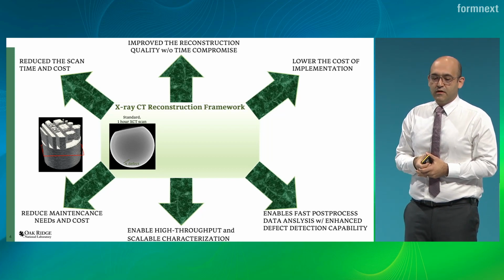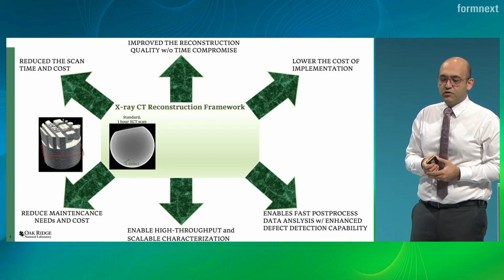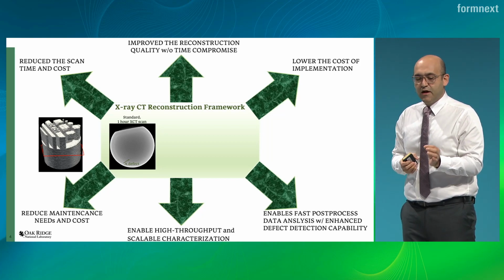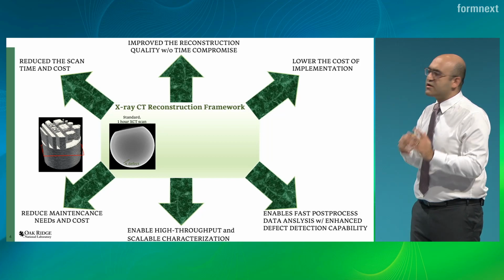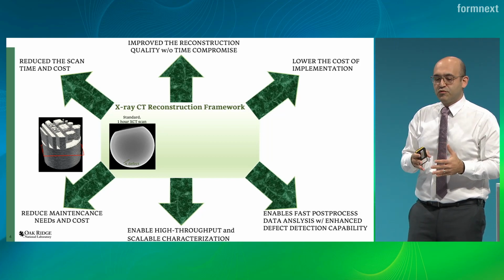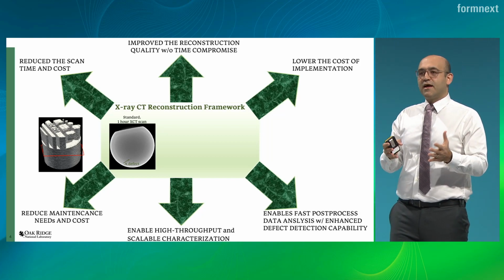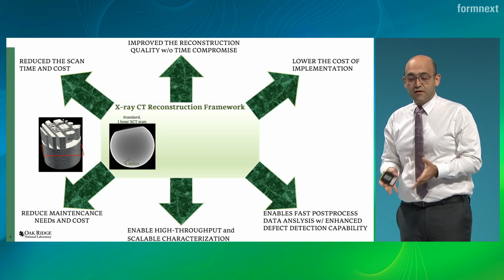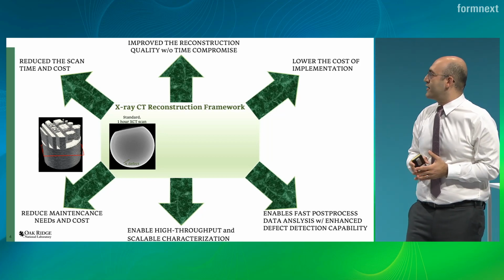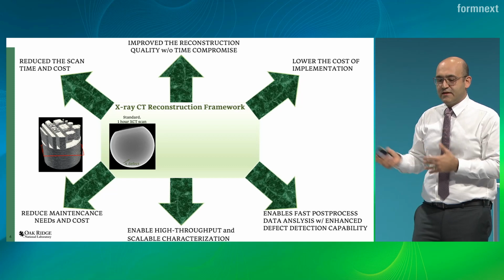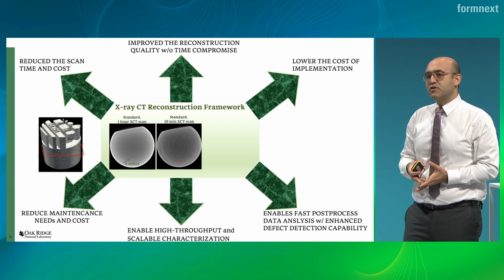and we cut through it to look at how the cross-section looks. You see small defects in there with a 1-hour scan. It's still very noisy. You can do some post-processing to improve that. But a 1-hour scan, if you have hundreds of samples, is not feasible. You cannot do hundreds of them and analyze them and send it back. So we need to reduce the scan time.